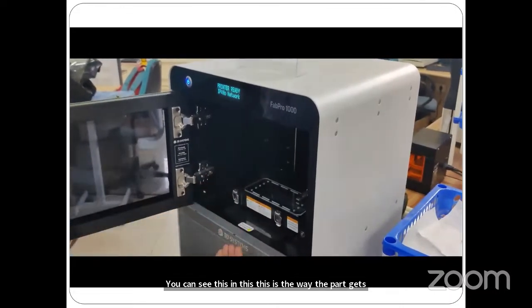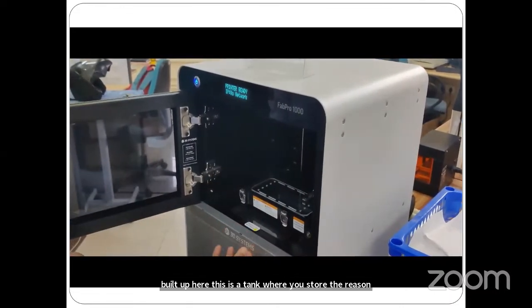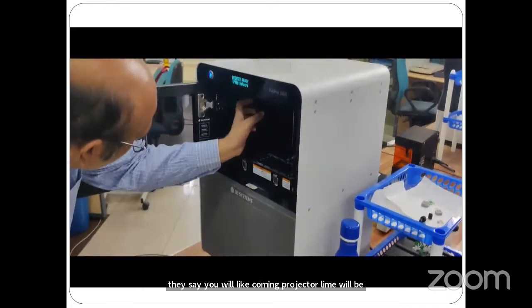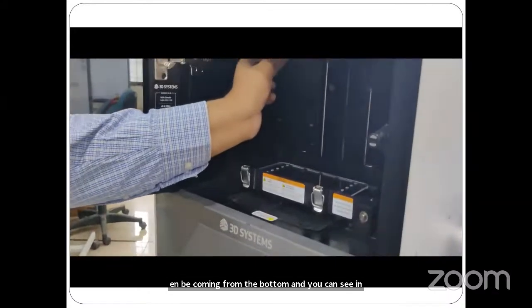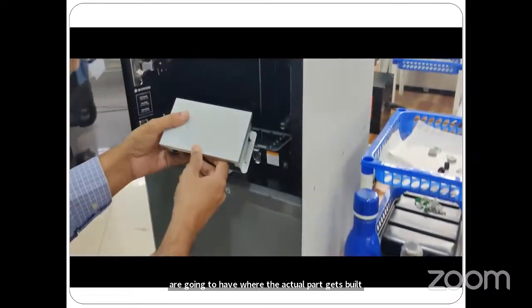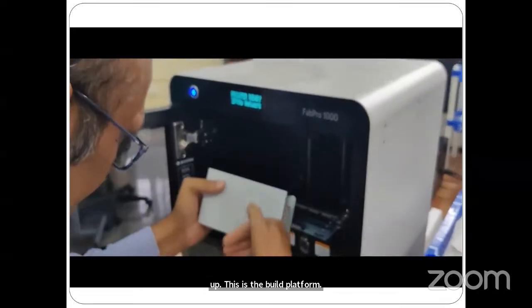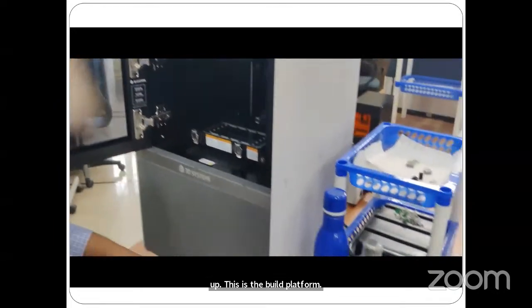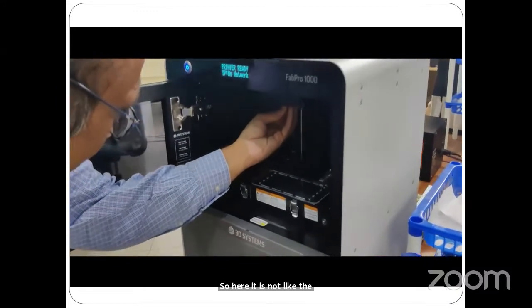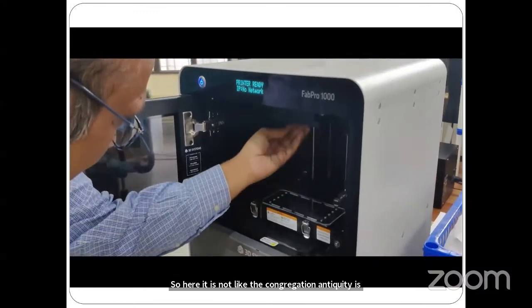And the light will be coming from the bottom. This UV light, the projector lamp, will be coming from the bottom. And you can see here is where the actual part gets built up. This is the build platform where the part gets built up, and you build in the reverse direction. So it is not like the conventional anti-gravity; the part gets built up from top to bottom.